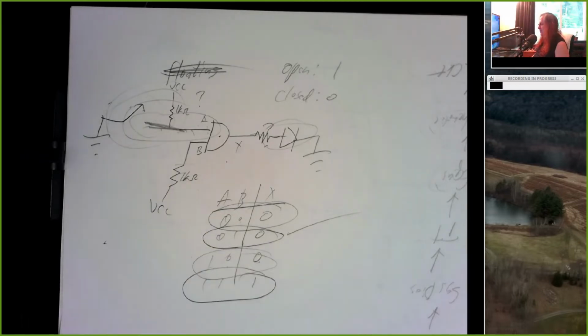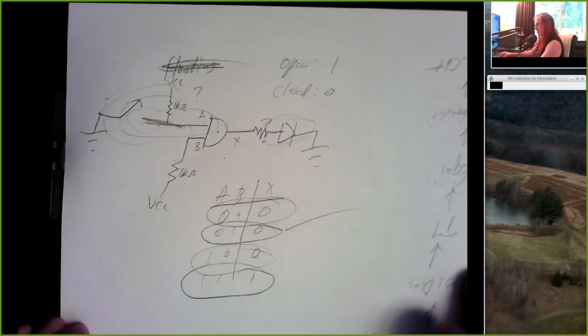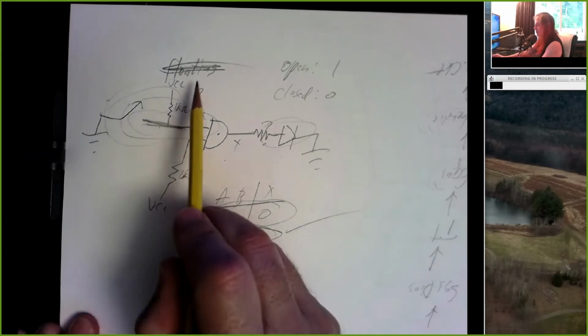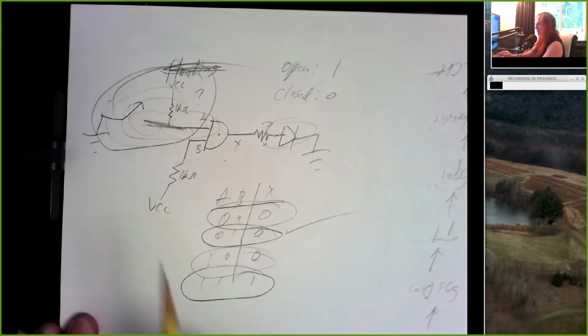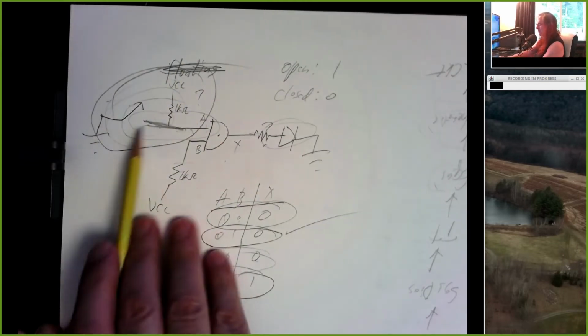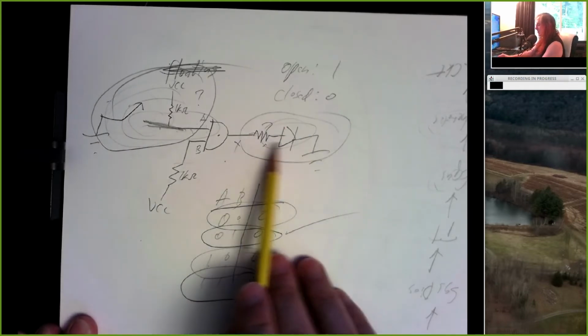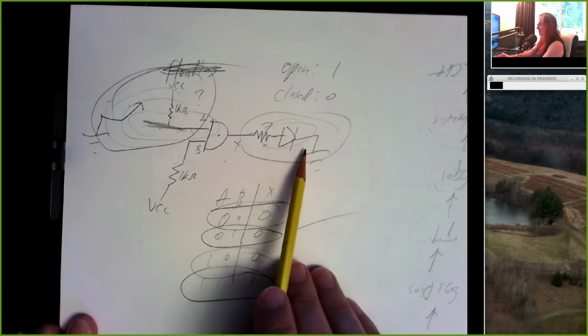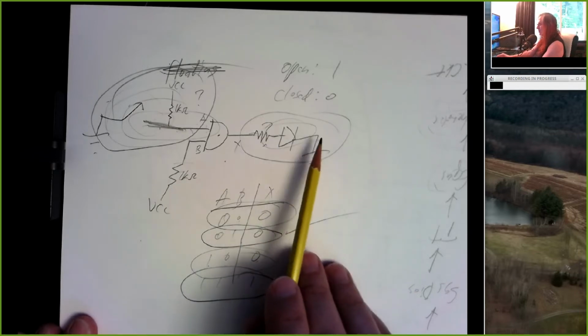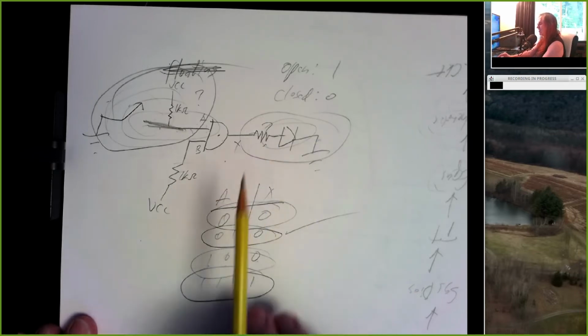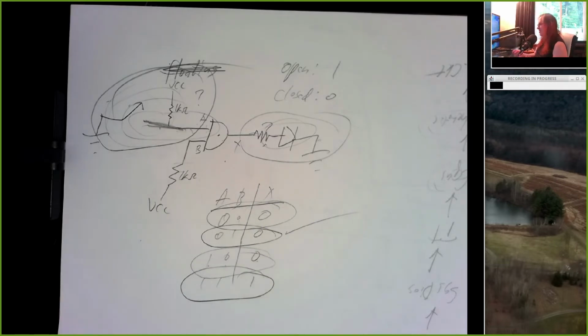For these kinds of circuits, switches and LEDs are always gotchas. And my only advice is, for switches, pull the input up to 5 volts through a resistor, and use a switch to let the person close it. For LEDs, always take the LED and run it through a 1K resistor in series, and if you want to turn it on, put the cathode to ground and feed the anode. If you want to do one of the fancy LEDs from that earlier lab, you can flip this around and so on.